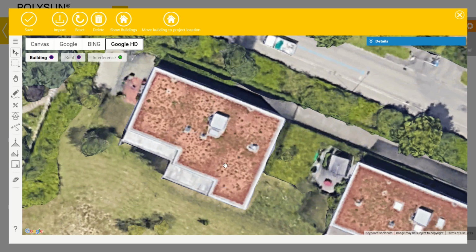The first step is placing reference lines to make the drawing of the building easier. The reference line tool can be found here beneath the pen tool. I select it and start drawing reference lines all along the outside of the building, so that we only need to connect the intersections of the guiding lines. You can also see that the new line automatically snaps to the existing reference line. Using this, I select the line easily.